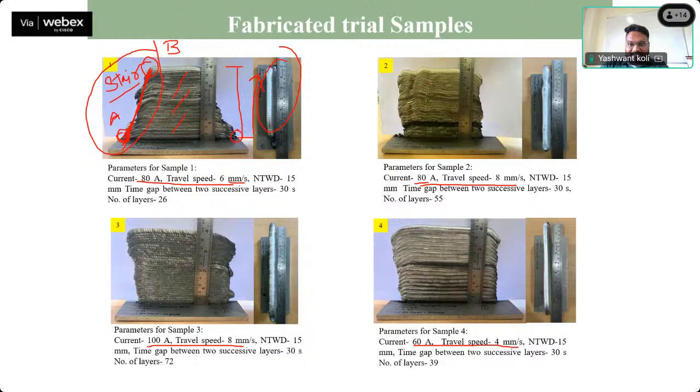And in this sample you can see one defect. After cutting we can see the porosity levels, or if we can go for 3D tomography, then we can check the porosity level in the bulk. And you can see this second sample is having humps. It's like camel humps, humping. So this is the second defect that I want to talk about.